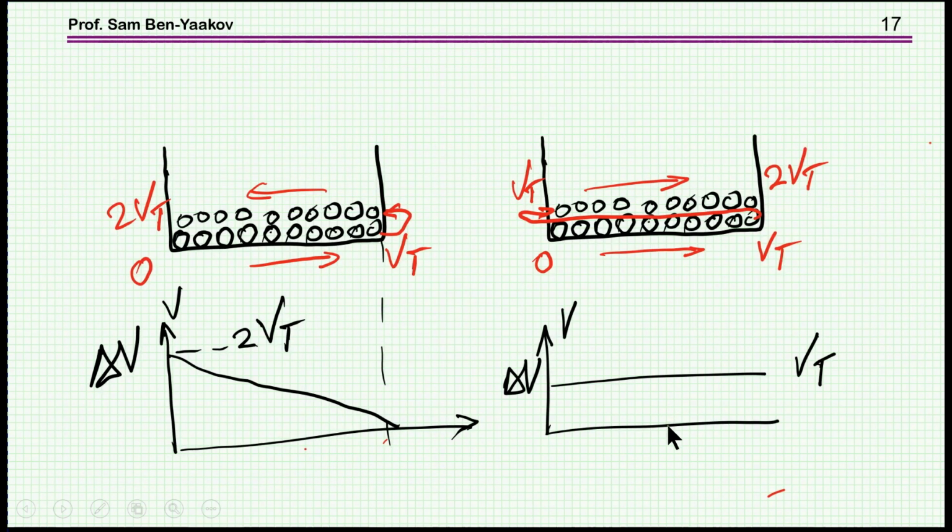Now, what are the practical implications of all what we have said here? In a conventional way of winding a transformer, you start from here, you put on the turn, then you go back here, and then you go all the way back. Now, in this case, obviously the voltage difference between these layers here is only the voltage of one layer, but here we come to a point where the voltage is twice, because we have a drop of one layer, then a drop of another layer. So this will be the profile of the voltage across this section here.